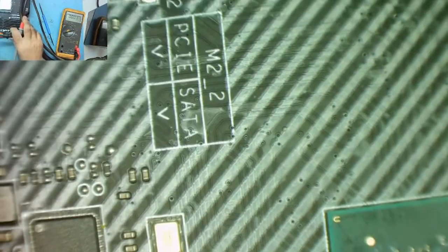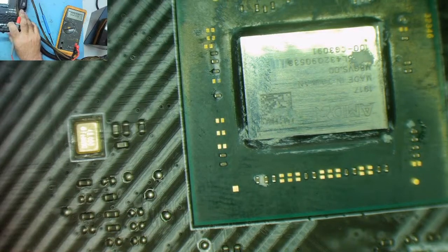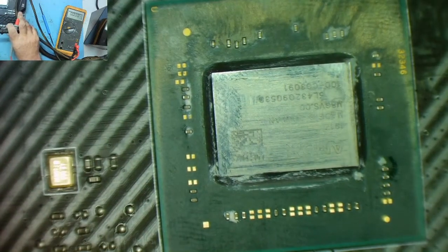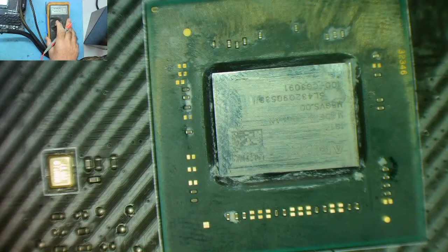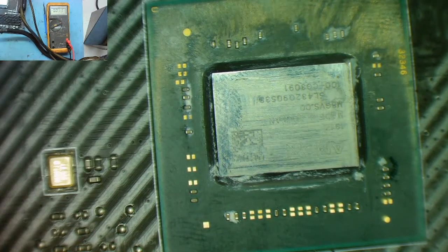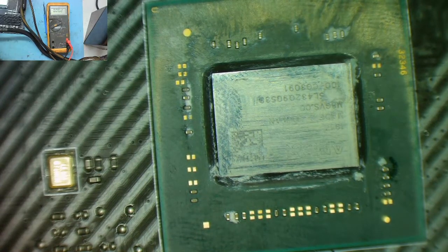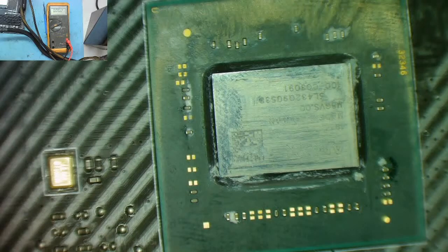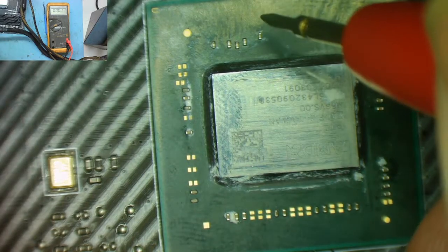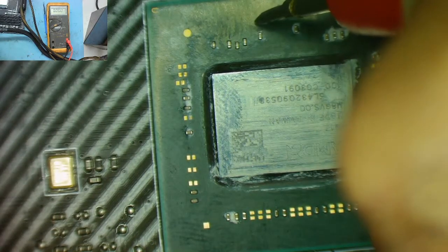Second place we need standby. The north bridge. Where are you? There, north bridge chip. We need to have standby here. Quite often this is a bit lower, it's quite often 1.8, it could be 3.3, depends on the chipset. The more modern boards seem to be a bit lower, maybe even lower than 1.8, 1.1 maybe, don't know. So I'm connecting the meter from ground, and again I'm going to look on the capacitors on here to see if I have any voltage coming in.